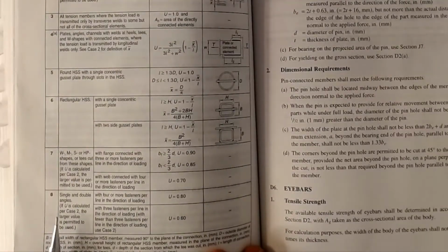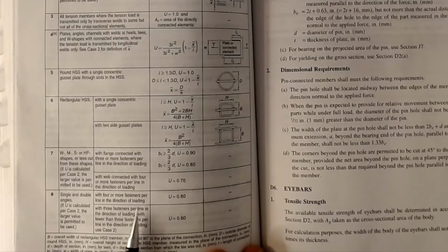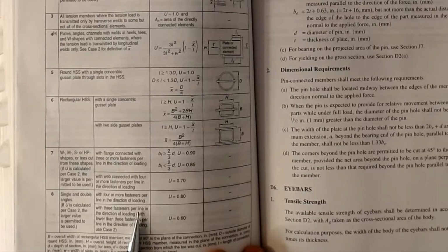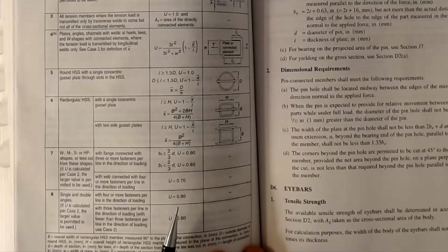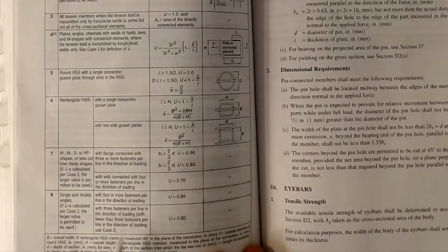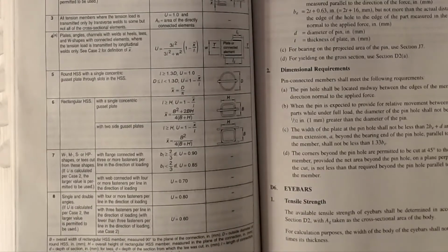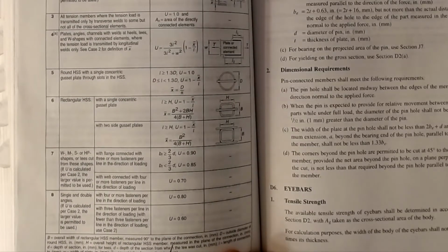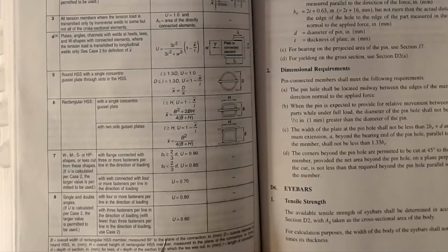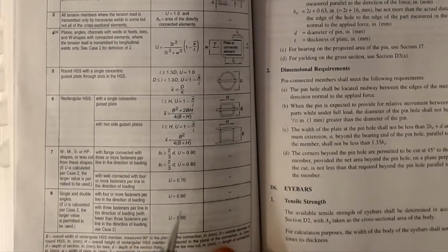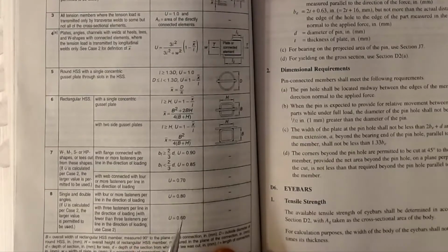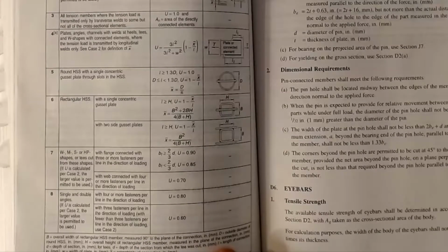And you can see, in this case, with 4 or more fasteners per line in the direction of loading, U is 0.8. With 3 fasteners per line in the direction of loading, or with fewer than 3 fasteners per line in the direction of loading using case 2, then U is 0.6. And again, that's kind of a reflection on growing that L length. So if you're just doing a preliminary sizing of a member, you don't know what the member size is and you haven't detailed it, these are good starting points because you'll never be worse than these values according to what AISC allows you to do.